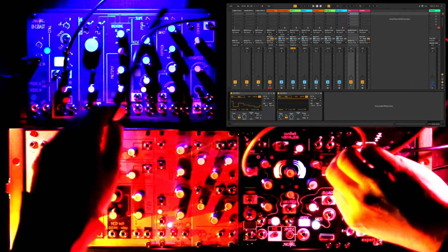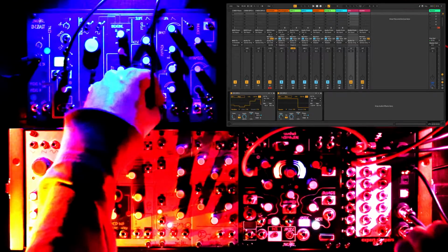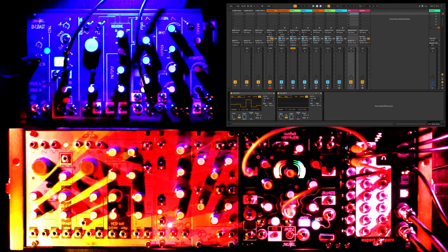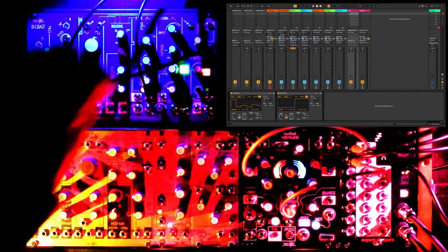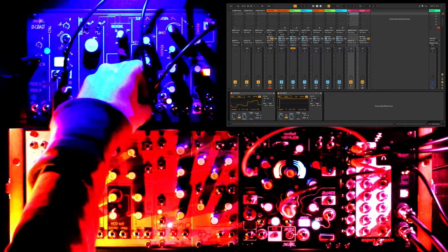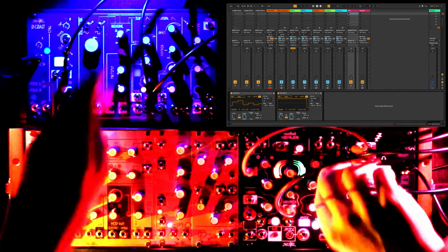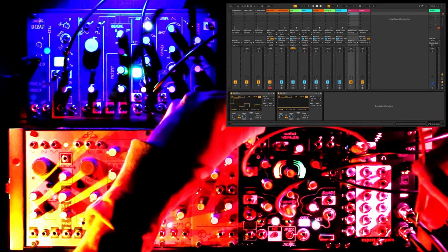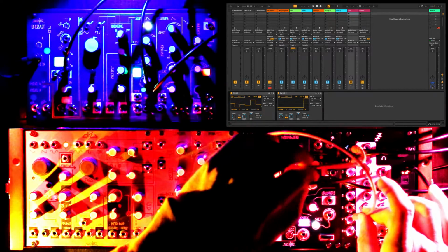We'll use another stackable cable to send the square LFO to the Zero Coast's gate input, and the Morphogene's vari-speed control, which will periodically raise the octave of the buffer. Using one last stackable, we're going to patch the slope generator of the Zero Coast to the Morphogene's slide input, set it to loop, and this will modulate the start position within the playback window.